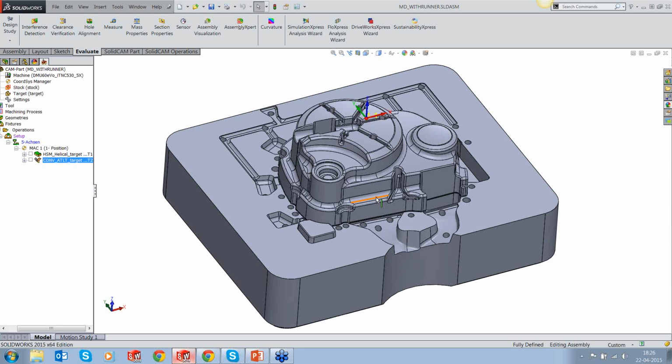We have actually those two quick questions. The first question was, I believe this also came in when you were showing the multi-axis roughing: is a floor surface necessary for multi-axis roughing? Yes, it is absolutely necessary because the whole algorithm or the whole software works on the principle that the tool is always normal to the floor surface. So you have to define the floor surfaces.